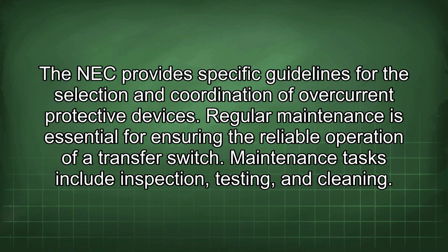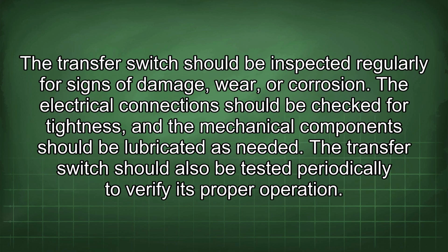Regular maintenance is essential for ensuring the reliable operation of a transfer switch. Maintenance tasks include inspection, testing, and cleaning. The transfer switch should be inspected regularly for signs of damage, wear, or corrosion. The electrical connections should be checked for tightness, and the mechanical components should be lubricated as needed.